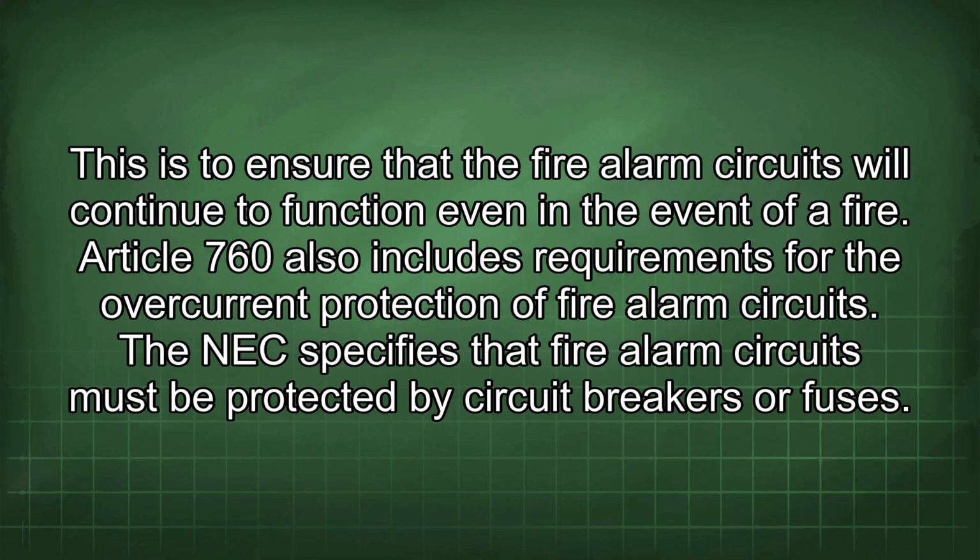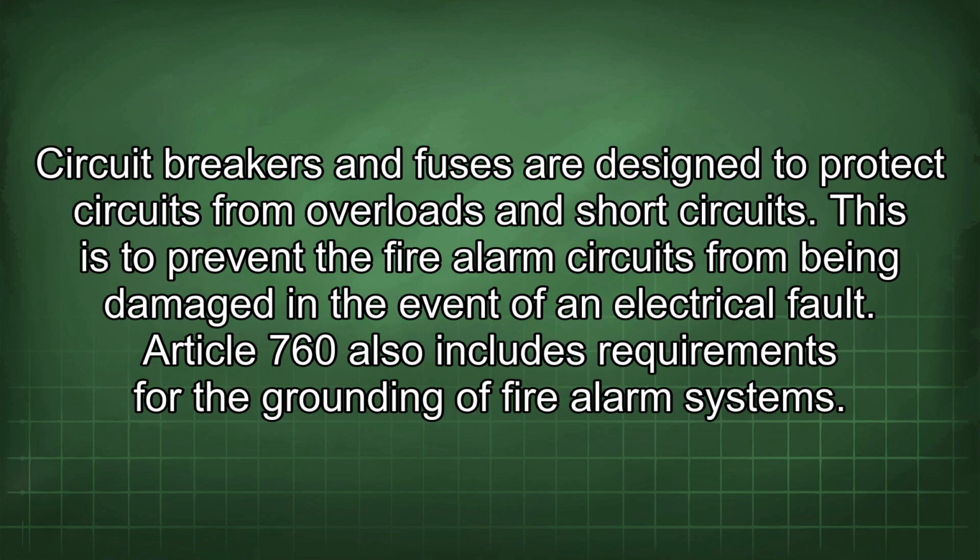Article 760 also includes requirements for the overcurrent protection of fire alarm circuits. The NEC specifies that fire alarm circuits must be protected by circuit breakers or fuses. Circuit breakers and fuses are designed to protect circuits from overloads and short circuits. This is to prevent the fire alarm circuits from being damaged in the event of an electrical fault.